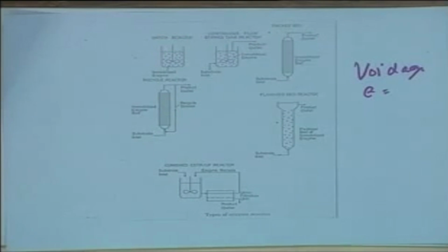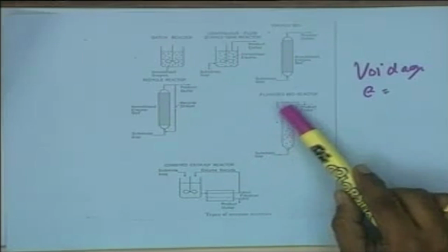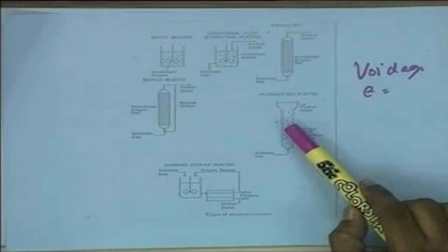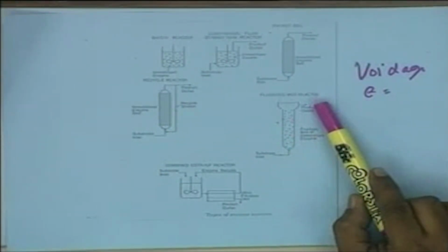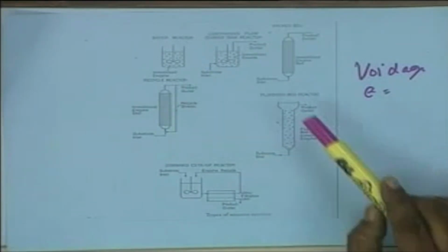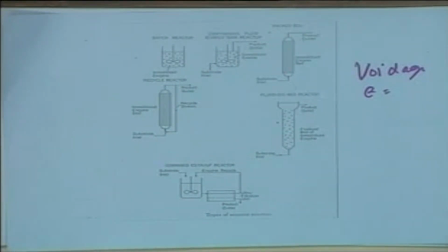Particle shape and size will control the voidage in the packed bed, but when you move ahead from the plug flow behavior and continue to increase your feed velocity to a level where the packed bed is disturbed, it gets fluidized. The particles are fluidized in the reactor system almost like as shown here, but not to the extent that the catalyst particles are driven out of the reactor system. They are retained in the reactor system. We call it a fluidized bed immobilized enzyme reactor.